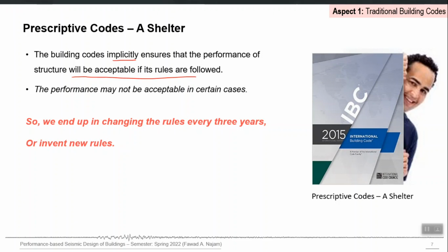You will not be able to tell what will happen if I don't follow a particular provision of the code, right? If it says that that much spacing should not be less than 4 times dia of the bar, you cannot explicitly check what will happen if you don't follow that, right? So all you have to do is to believe in the letter of the code, and it is the intention of the code that you will be able to provide the public safety and convenience.